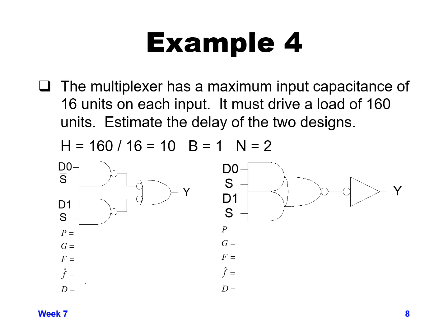Now let's start going through the parameters for the design on the left. When we want to know our parasitic delay through the path, what we need to do is take the parasitic delay through each of the gates and add them together.